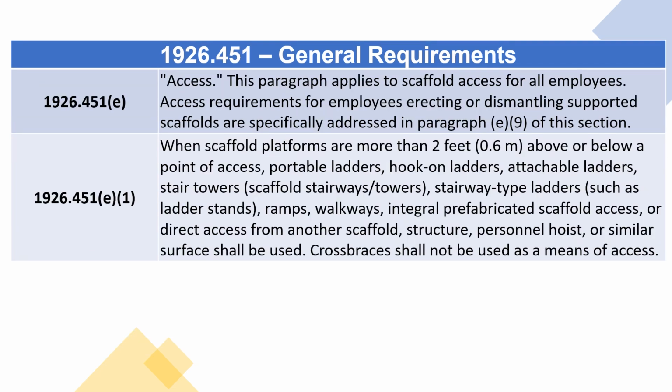1926.451(e). Access. This paragraph applies to scaffold access for all employees. Access requirements for employees erecting or dismantling supported scaffolds are specifically addressed in paragraph (e)(9) of this section.